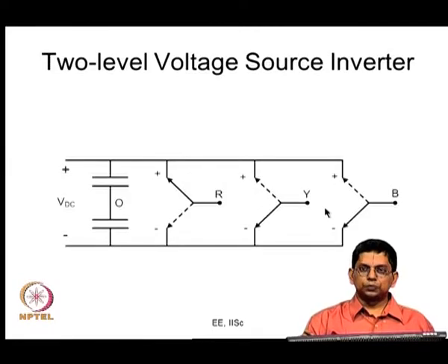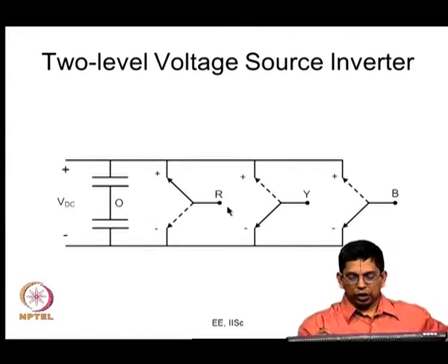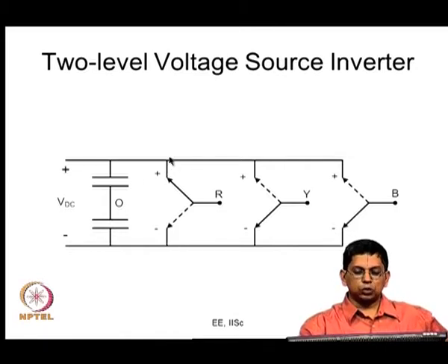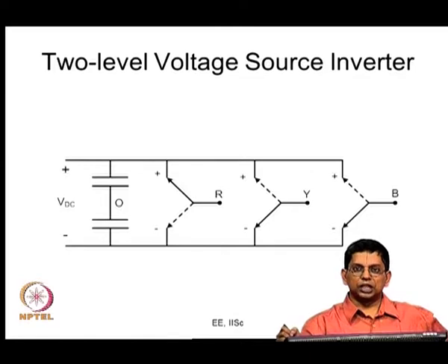Alright. So, voltage source inverter. You have a 3 phase load, and the load is presumed to be inductive. You see that these are all poles, so the load terminals are connected to the poles of the switch, so that the inductive circuit will not get opened out, and then the throws have the DC voltage connected across them. You switch, and this is how you connect. You have the capability of connecting the pole either to plus VDC by 2 or minus VDC by 2, at the top or bottom here, and so it is possible to apply alternating voltages here, and you do this as an inverter.